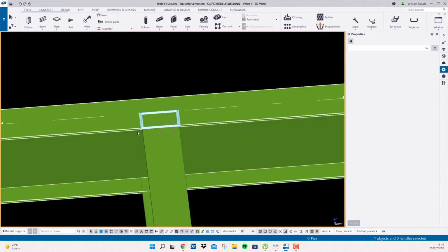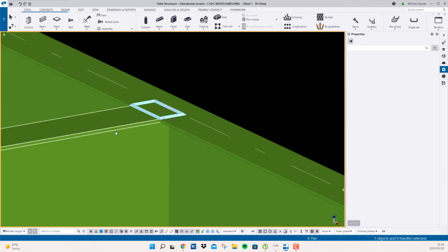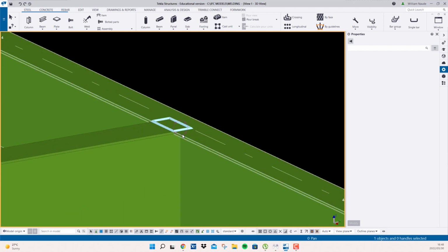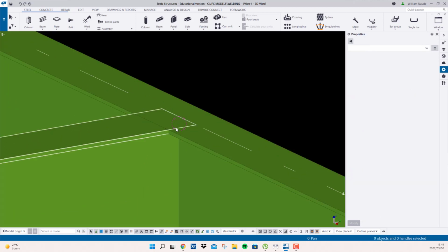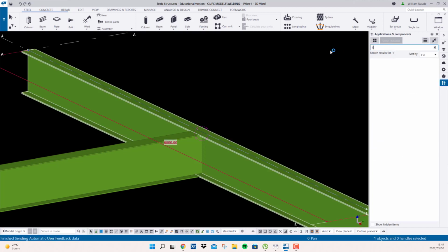Now currently it's not working properly because I just simply added an item, I pressed it in, and that's it. I didn't really create a cut of it and remove. So currently Tekla is in an error item. So I can choose this and delete it, and the weld will go away. So again, if I choose my assembly, it will be two different parts again. So now let's just put in a normal end plate.